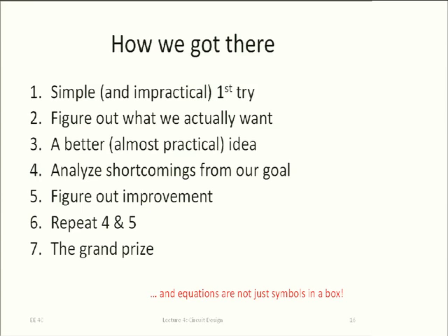So one thing, when my circuit doesn't work, and even if it does work, the first thing I usually do in the lab is I take my voltmeter, and I know on this component here I should have the supply voltage, 5 volts. I check, do I really have 5 volts there? And 99% of all the time, I just wasted my time, right? Because, of course, I've built my circuit that I have the supply there, and lo and behold, it is there. But in that 1%, when it's not there, I save myself hours and my last few remaining hair fixing that problem before coming up with the most unbelievable explanation of what's going on. So first, try to make sure that you're sort of on the right path.